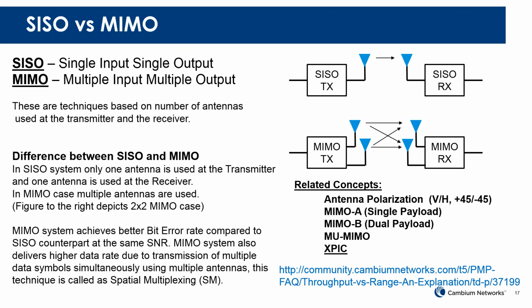And then you have some logic connections between the two radios so that they can communicate with each other and know what each other is sending out, and if they know what the other radio is sending out, they can know what not to listen for. And this is completely oversimplifying it. But generally speaking, if the two radios know what each other are sending, then they know how to cancel out what that one is sending, and therefore be able to distinguish only their wanted signal. That's what XPIC is ultimately doing.